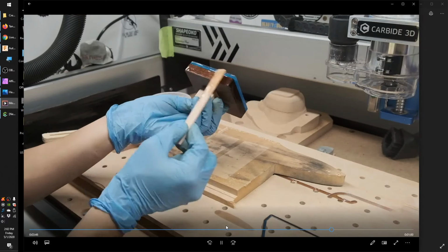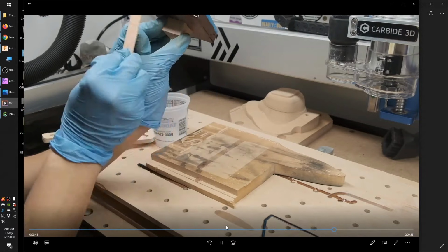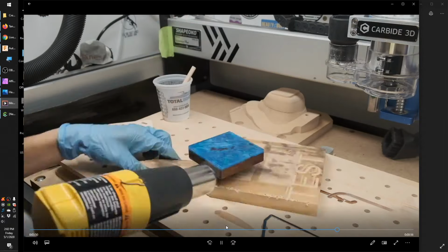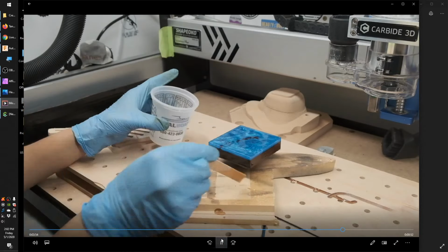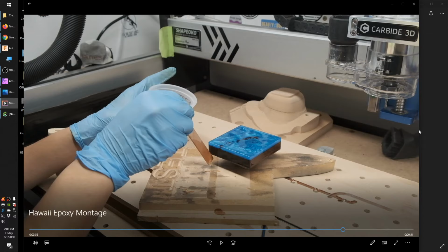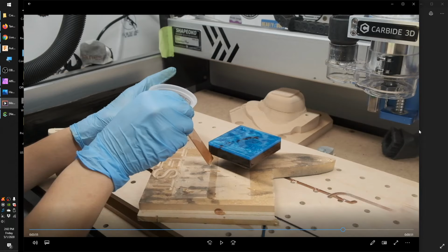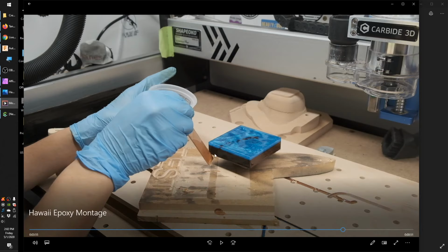I used a popsicle stick to smear on some tabletop epoxy, so it's just a slightly thinner version. It's meant to go on thinner, it self-levels. You should probably use a high-quality brush with this, because if you apply it too thick, it'll go over the edges, and it's going to start building up. So what I'm trying to do is scrape off just the little extra lip of epoxy that's been collecting on the edge. And if you apply a really thin coat, that's not a problem.